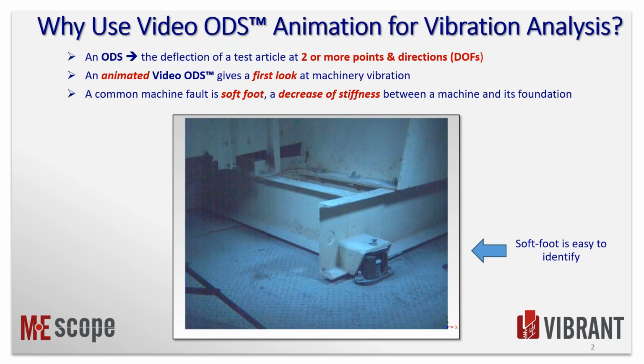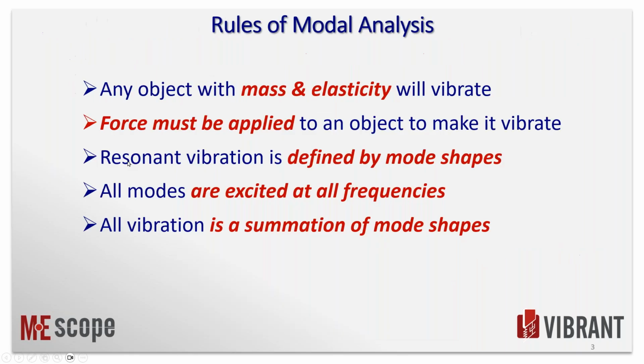My cell phone, an iPhone, and this video was taken at 60 hertz, or frames per second. So that's very common among all the cell phones. But the Google and the Apple phones can sample at up to 240 hertz. So if you multiply that by 60 RPM per hertz, that takes you up to over 7,000 RPM. So you can analyze a lot of data and look at a lot of vibration problems, certainly in larger machinery where the frequencies are lower.